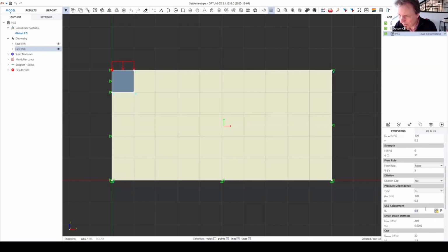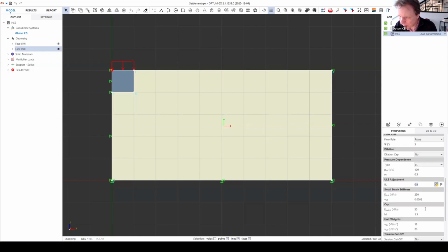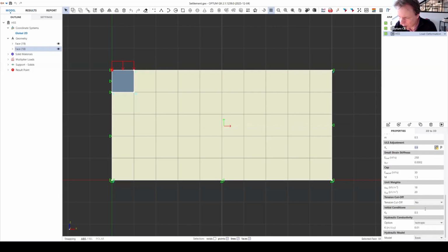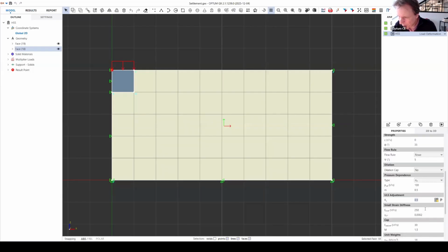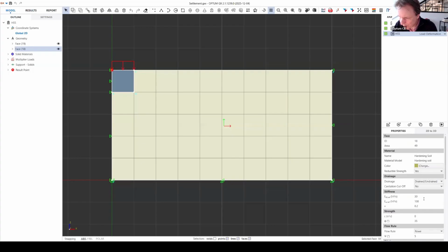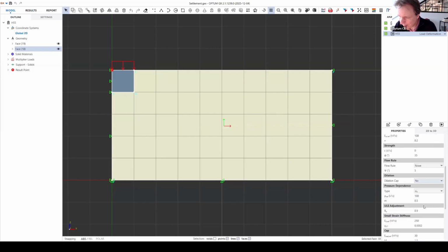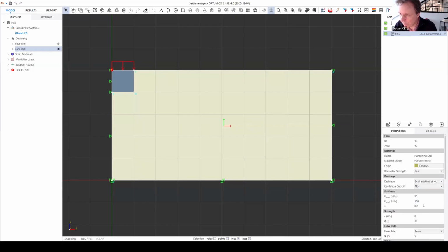We will have as well in the new year a webinar on some of the more complex models, including this one here. I don't really have time to go through all of it today, but just for the purpose of this, the question was how well what do we get here with an E50 ref of 30 MPa, EUR unloading-reloading of 100, and then this 250, compared to Mohr-Coulomb.